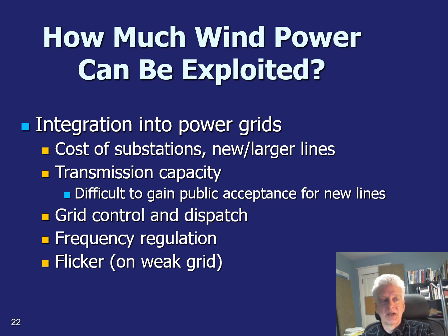So power grid management, that has a whole technique, a whole science for managing the sources that are there, controlling their frequency. And when you're on, let's say, a remote location where the grid is just a single line that both feeds residents there and now is taking your wind, you might be introducing a lot of power, and you can actually cause people's lights to flicker. That's come up in the past.